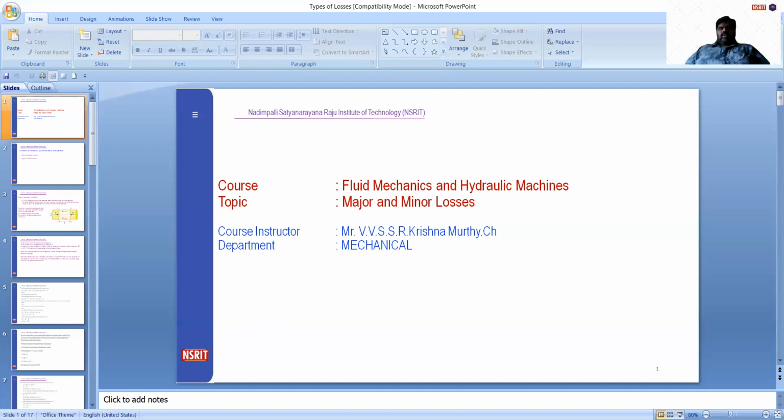We said that there is a frictional force acting opposite to the pressure force, and the frictional resistance is expressed with the help of Froude's formula. Froude's formula states that the frictional force is friction with respect to wetted area into velocity square, where F dash is the frictional resistance per unit area per unit velocity square. The wetted area of the pipe is the circumferential area, 2 pi r L, and 2r can be written as d, so pi d L into v square. So total F is equal to F dash pi d L into v square.